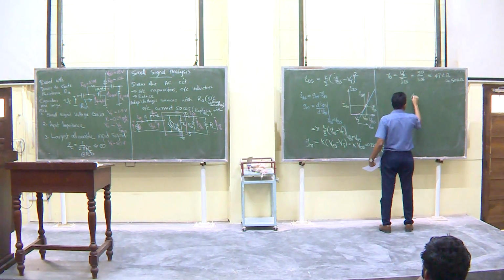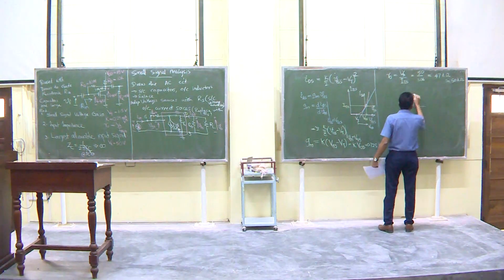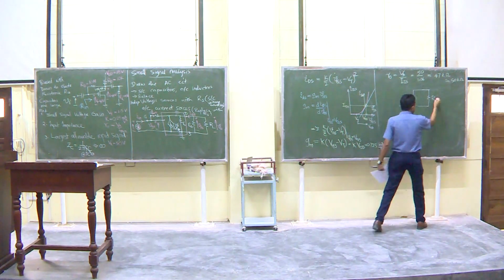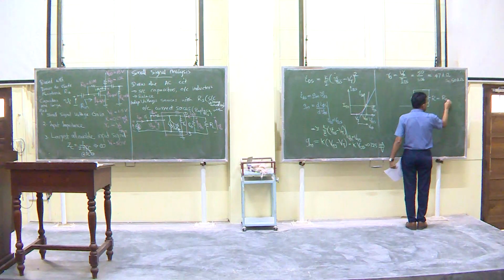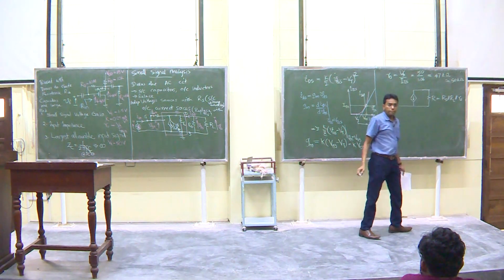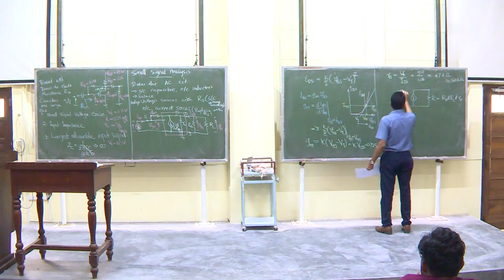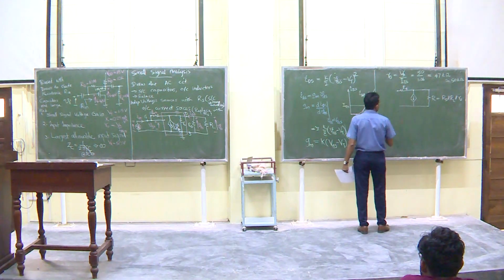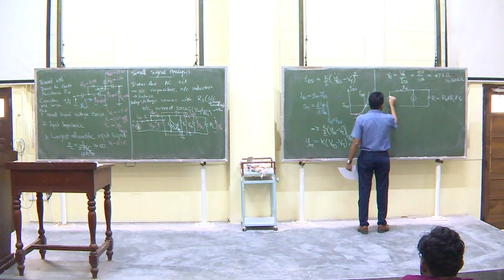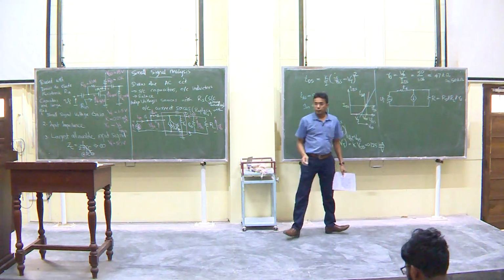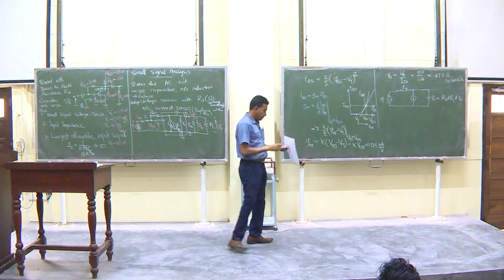So you have the MOSFET between drain and source, and then there is this single resistor R whose value is RD parallel RL parallel r_o. And then you have a resistor between the drain and the gate, which is RG. And then you have the VI. Okay, so that's basically what you have in here.